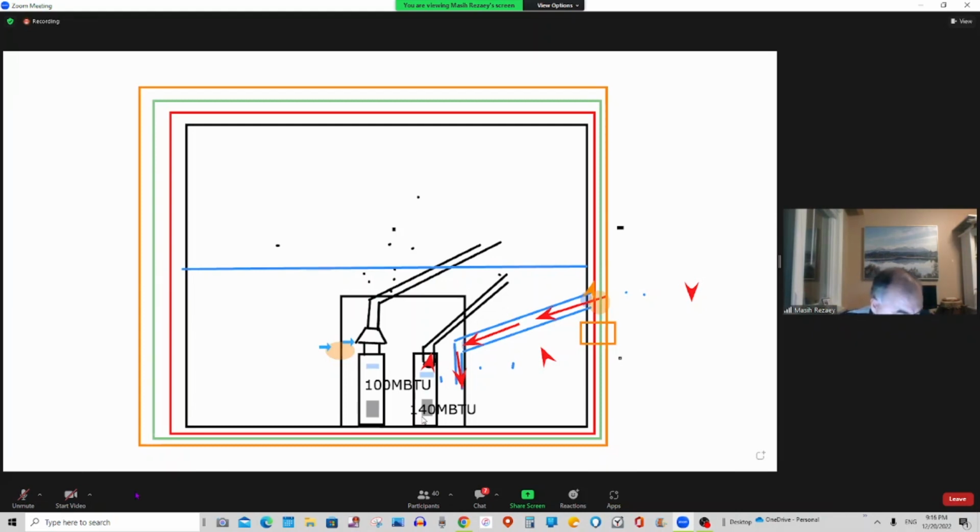Okay, let me repeat it one more time. On clause number 8.2.2, it says first you use table 8.1 with the input of only those appliances having draft control. Only mine here has draft control, which is 100,000. I go to table 8.1 and I see it's 14 inches square and 4 round.